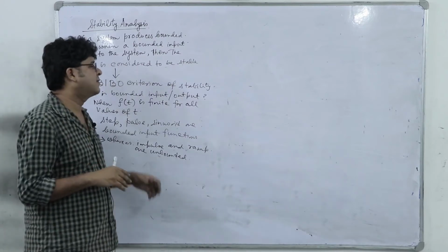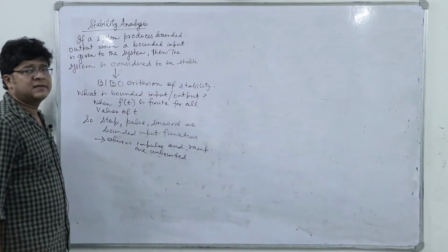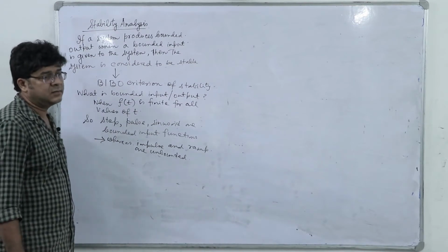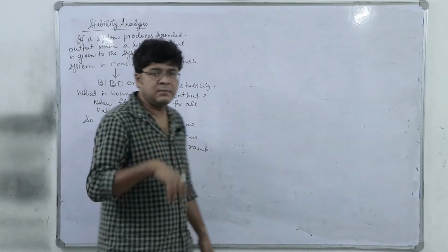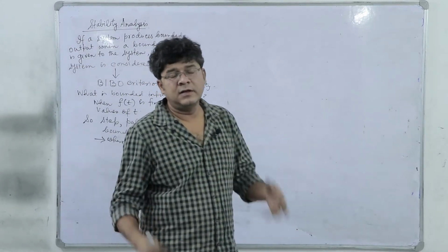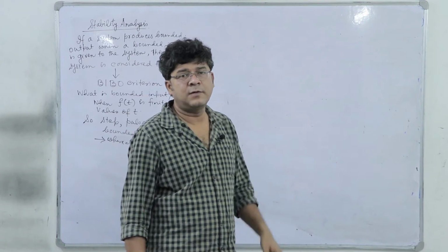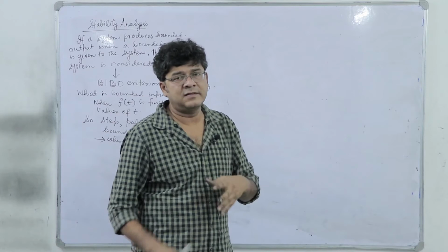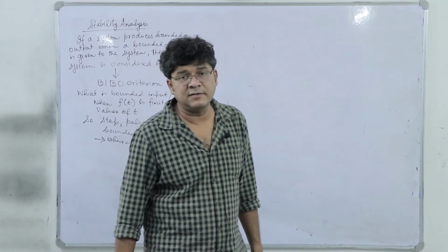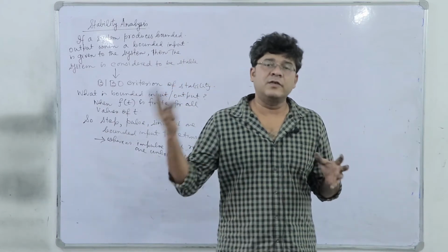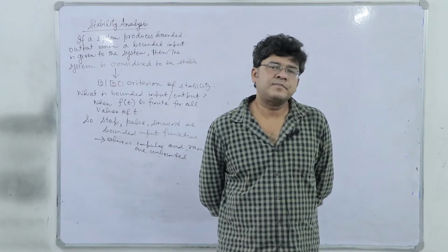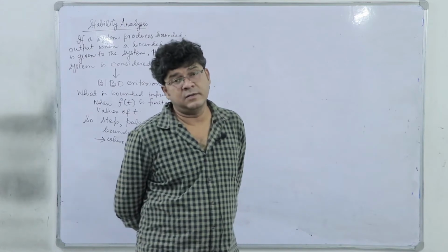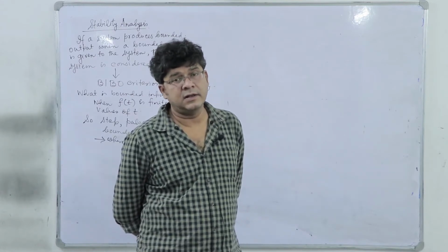Now, the point is, we cannot go on exploring the exact response of the system, because then we have to give a step input, go for the Laplace transform, where the transfer function must be multiplied with 1 by s, then go for the tedious Laplace inverse transform, generate the time domain function, and finally from there conclude whether the system is bounded or unbounded, right.